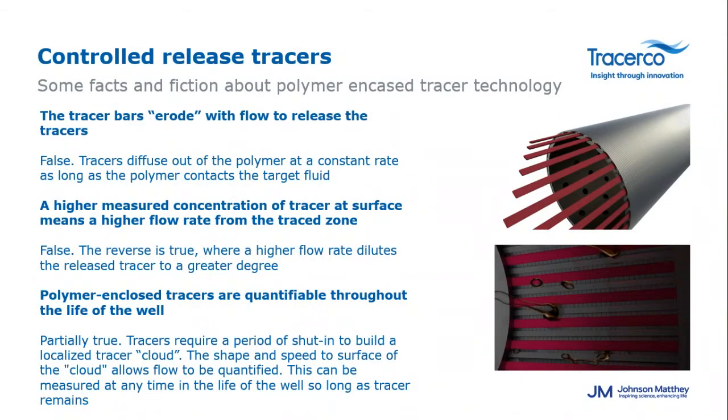If you have or have not had exposure to solid tracers, here are a few bits of information that are important to know. 1, solid tracer bars do not erode. The tracer is diffused out of the polymer, providing linear release. 2, high concentrations of tracer from the solid does not mean a high flow rate. The reverse is true. A higher flow rate dilutes the release of tracer to a greater degree.